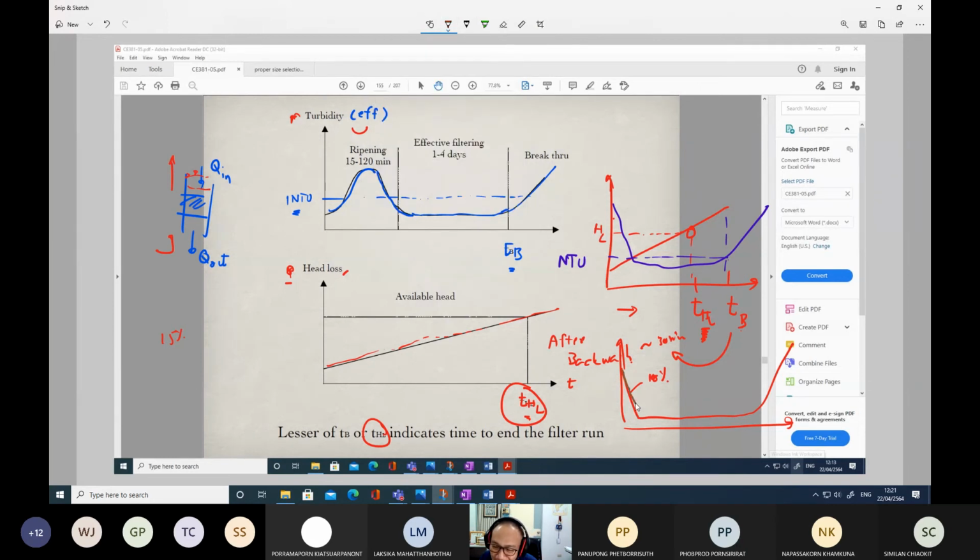Still, the turbidities will decrease and then reach the lowest point. This is 50% clean in terms of time or in terms of volume. It doesn't matter, but it's not 100% perfectly done. So if it's only 50% clean, it's also not a problem. But the only thing is, if you operate it for some time, it will reach the maximum capacity sooner.